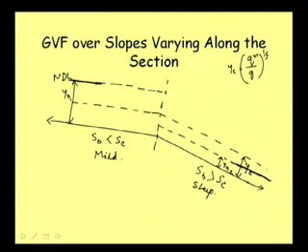Well, now let us see how we can do that. In this second portion, it is a steep slope. So, the flow is below critical depth, and as such the uniform flow occurring is supercritical flow. As it is supercritical flow, any disturbance at the upstream point will influence this flow.